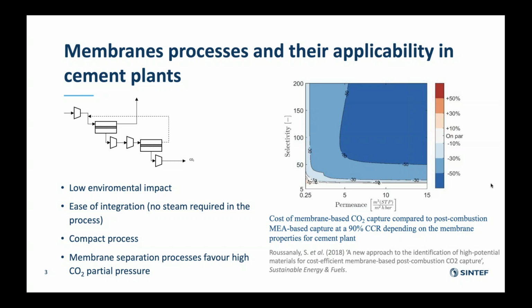So this figure shows the cost of membrane-based CO2 capture compared to MEA post-combustion capture at 90% CO2 capture ratio. The important point to note here is that both the membrane and MEA are considered to be at a high maturity level, so they are at the same maturity level here. And what this figure shows is that for a wide range of membrane properties, both selectivities and permeance, the membrane outperforms the MEA by a large margin. So this is what we can say from just the membrane perspective.